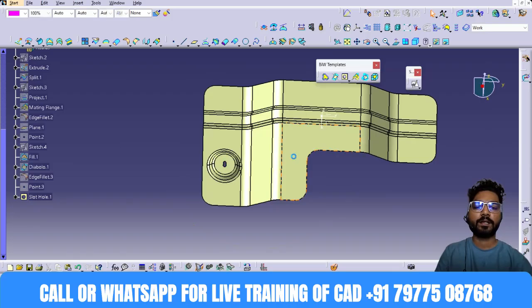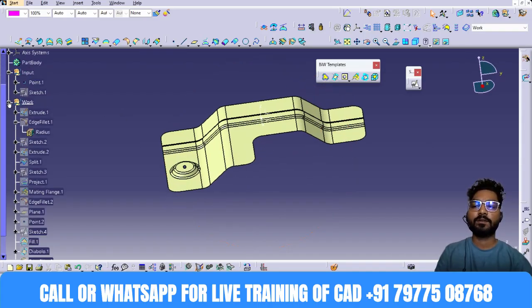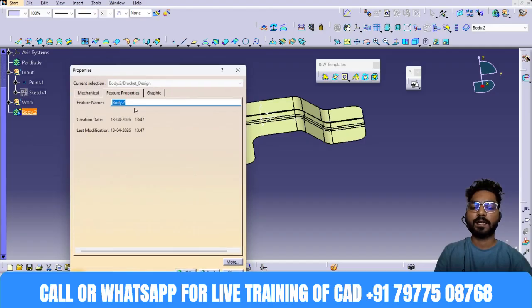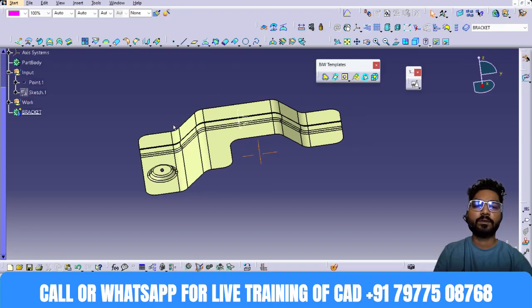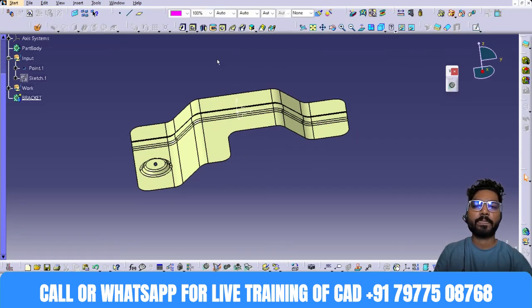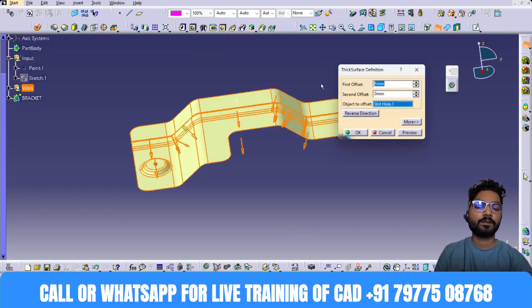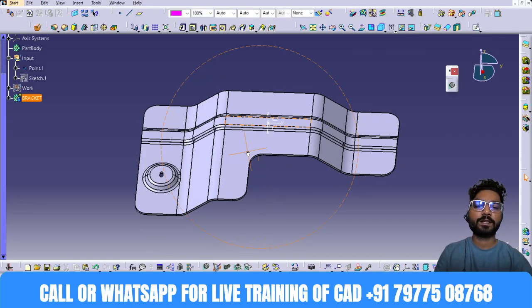And now this concept is ready, but at the end we want to convert it into a solid, right? So here we can insert a body, and in the properties we'll add it as a bracket and name it. Then here you have to apply the thickness. So we'll shift to the mechanical part design workbench, and in part design we are going to add the thickness. So you can take the thickness command, select reverse direction, and a 3 mm thickness will apply. So you can see now our solid bracket is ready.